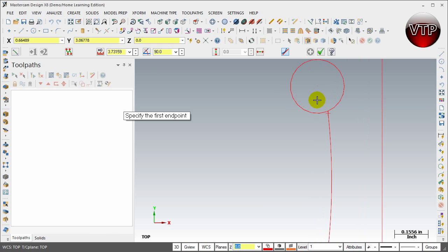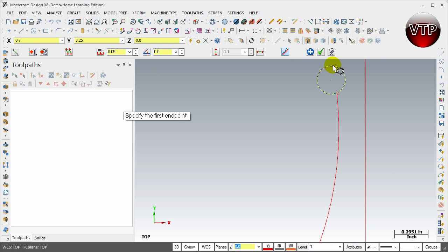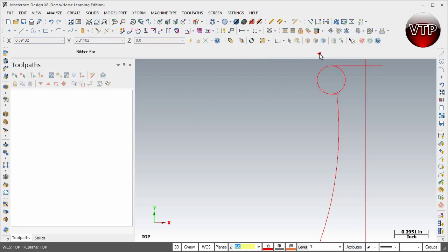So go ahead and minimize this and let's go ahead and create some lines that are connecting the circle to the point. So this circle to right here, and then again zoom out real quick, this circle to the line. So you're going to notice that it doesn't actually snap onto here, so just go ahead and go past it because we'll be cutting those lines anyway, and click on apply and OK. And let's go ahead and do some trimming now to clean things up a little bit.